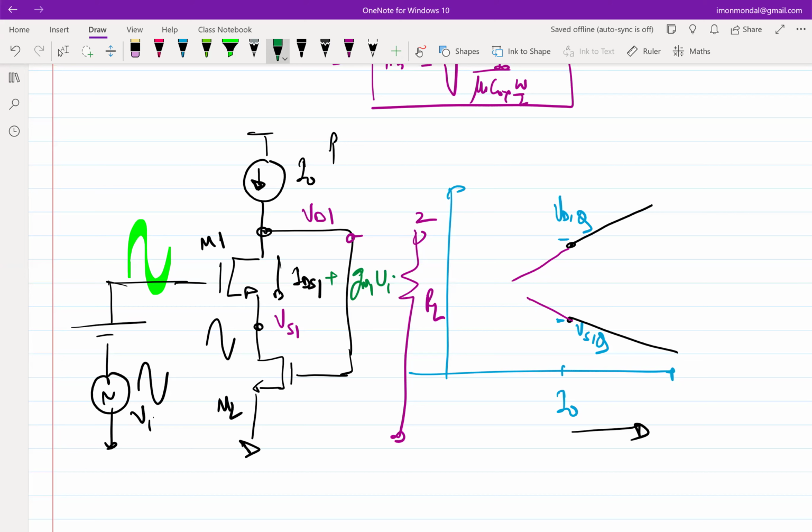Put a capacitor to any constant voltage, ground, for example, right? So let's say I call it C1, right? So if C1 is infinitely large, for any incremental current, the capacitor impedance will be shorted.